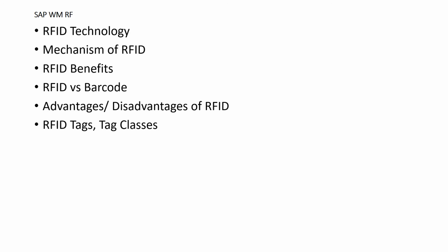These are the simplest type of tags, where data, usually a simple ID number, that is EPC, is written only once into the tag during manufacture. The memory is then disabled from any further updates. Class 0 is also used to define a category of tags called electronic article surveillance, EAS, or anti-theft devices, which have no ID and only announce their presence when passing through an antenna field.